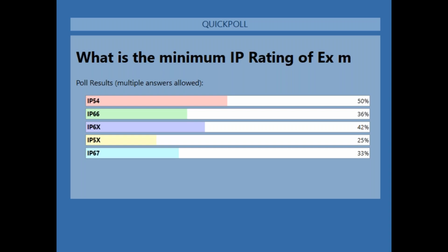So anybody who tells you you don't need an IP washer to maintain IP54 with 6 millimeters of threaded entry, you may want to read the standard and actually follow the certificate and the manufacturer's IOMs. The minimum IP ratings for dusts, you can be looking at IP5X or 6X. And for gases, GA, GB, GC, or underground mining, MA, MB, you'd be looking at IP54.